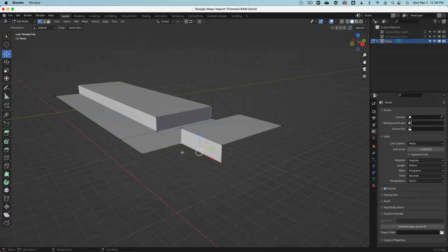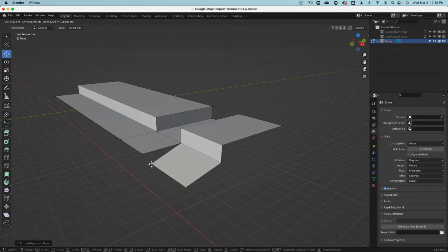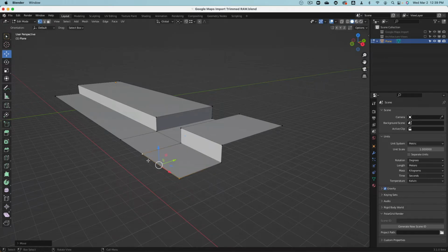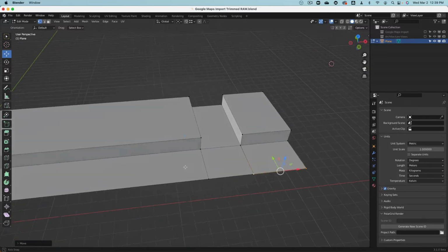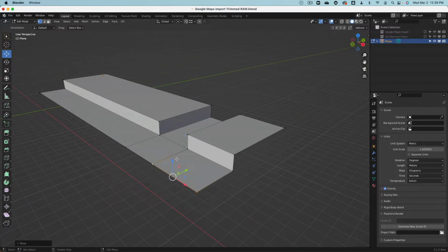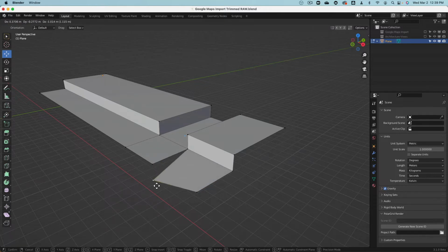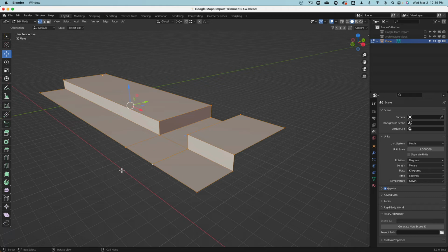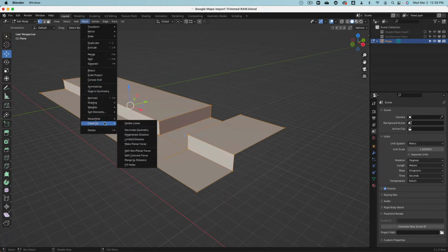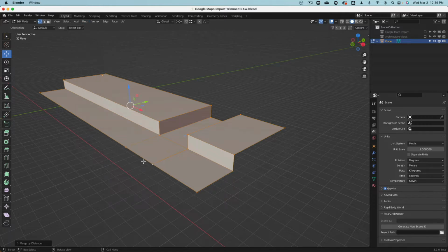Okay. I can actually also select maybe these two points, press E, move this out, go to here, G for move, hold Control and snap it to there. So without the F to fill. The only thing is I need to be careful that this is not connected. So I can press A for select everything, go to Mesh and say Merge by Distance. One point removed. There, it's joined.